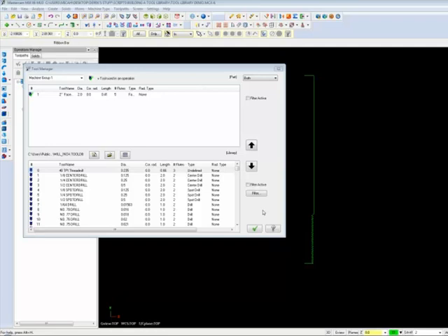Oh, and I hear Jay just jumping online there. Been trying to talk for a moment. Every time I said something, nothing happened. It took me a second to remember what Mike was talking about with the DB. Yeah, some of the newer stuff when it comes to the X7. If you put some of your tool data into DB format in X6 now, you'll be able to move some of that data into the newer tool manager, where in the older one it's going to be harder to get some of your existing tools and data in if you're using the older format, for example, X5 and earlier.